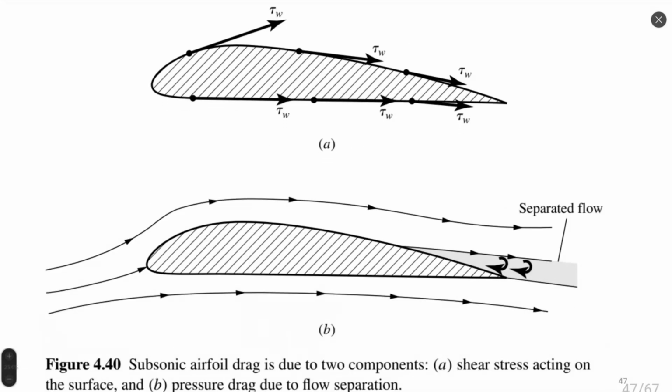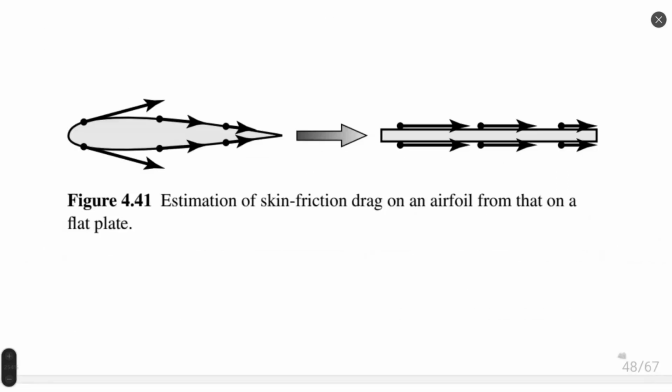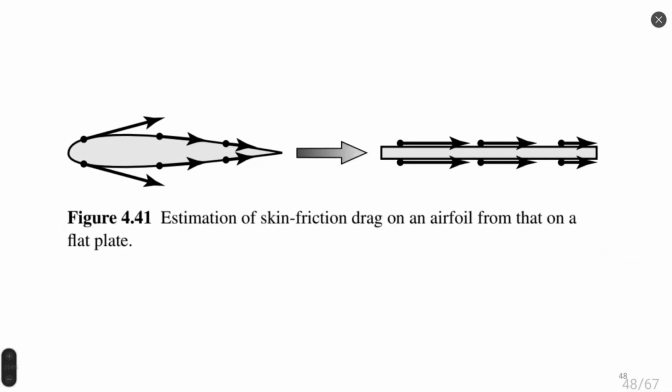Another important aspect is also flow separation. We must reduce volume of flow separation, strength of flow separation. We must have flow attached to our airfoil as long as possible. And this is another objective of numerical simulation in many cases. So airfoils working at high angles of attack produce high value of lift and high lift to drag ratio. Anderson explains this from point of view of boundary layer. I think we can